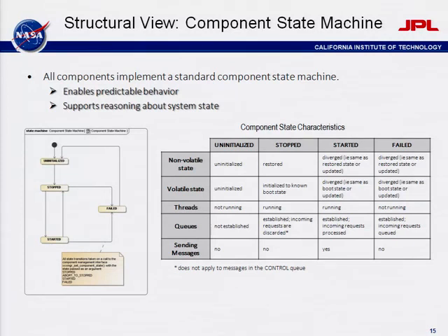When you start up a system, you come into the uninitialized state. In this portion of the mission, your non-volatile and volatile states are both uninitialized. You have no threads running. Your queues have not been established, and you're not sending messages.